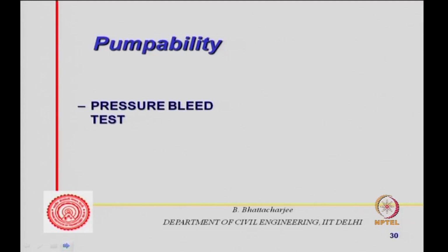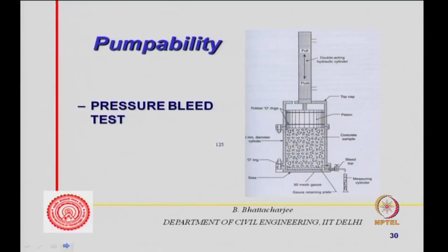Pressure bleed test is the one test which is used for pumpability. Now, this equipment looks like this. You have a bleed tap here. There is a standard mesh here. Here is the concrete, and there is a piston through which you apply a standard pressure.